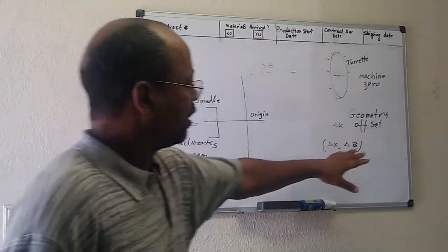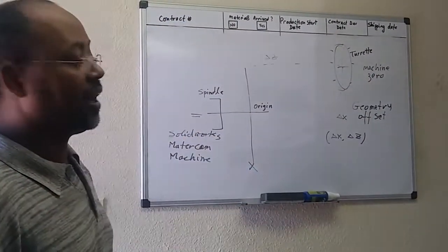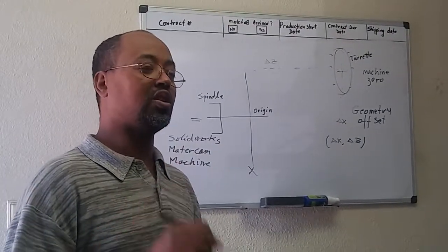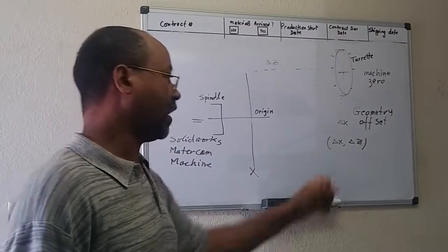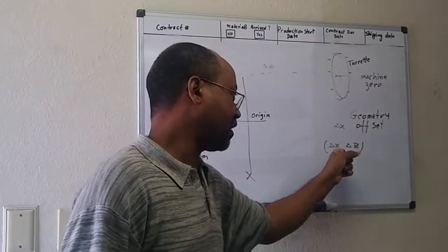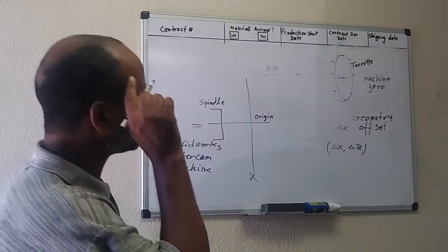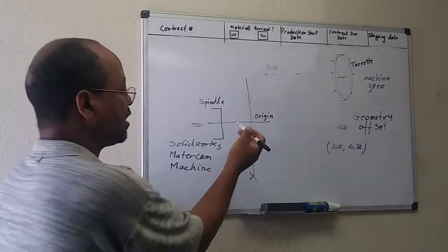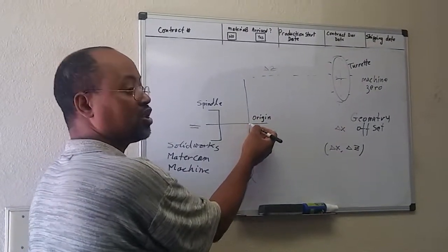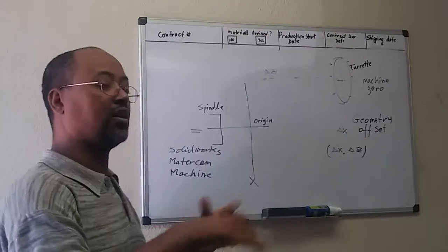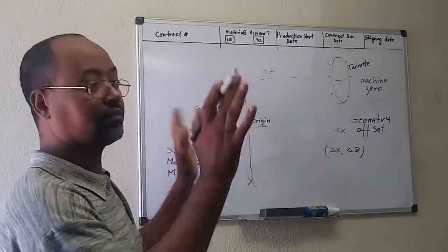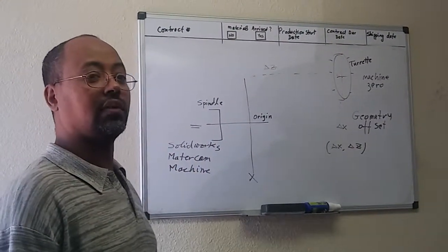So today's lesson is nothing but how you can set the zero position of every tool. It's geometry offset, delta X and delta Z. To do what? So that the machine's tip is back here at the zero position. So we enter all those offset values and what?